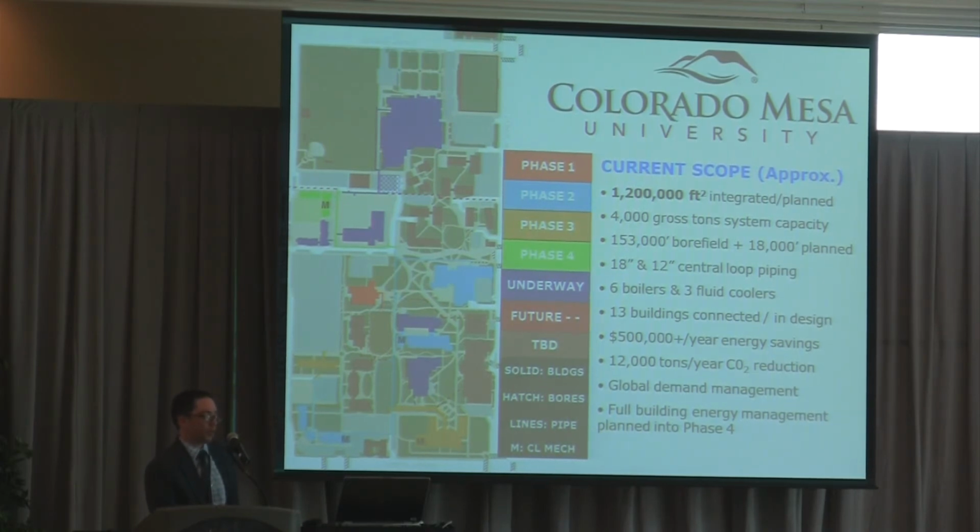And if any of you have experience with geothermal, you may notice that 153,000 feet of bore field sounds like a lot if you don't have experience with geothermal, but to do 1.2 million square feet of service, or 4,000 tons of service, with 153,000 feet of borehole is a ridiculously small amount of borehole. The reason for that is because the system is so diverse that the majority of the energy delivered by this system is recovered and coming from other buildings. It's actually not coming from the ground. The geothermal has become, in a sense, an auxiliary to this system, and the primary functionality of the system is just moving energy from building to building.